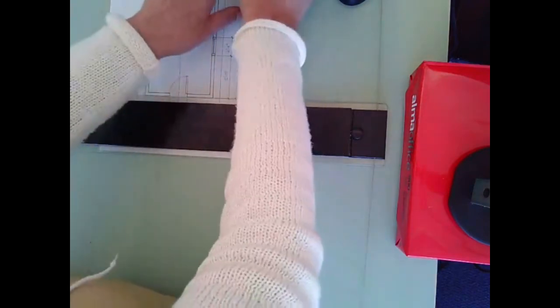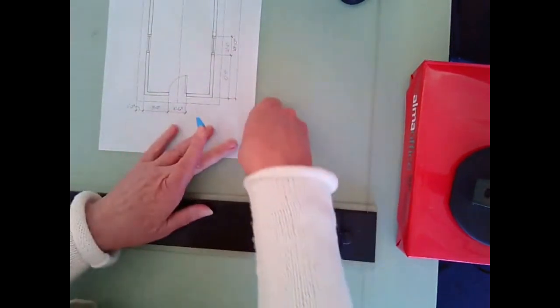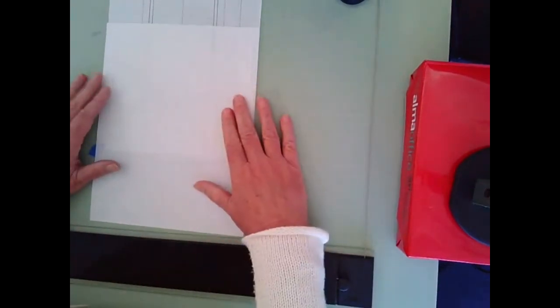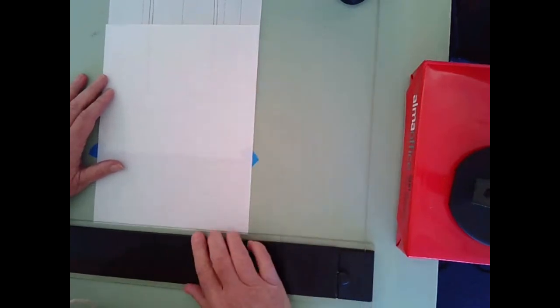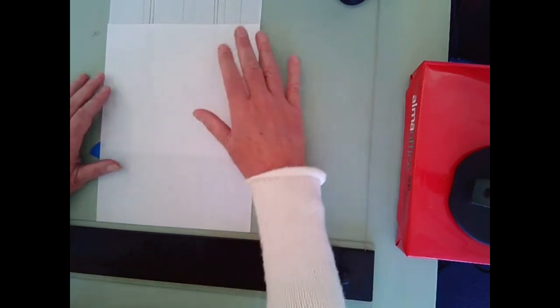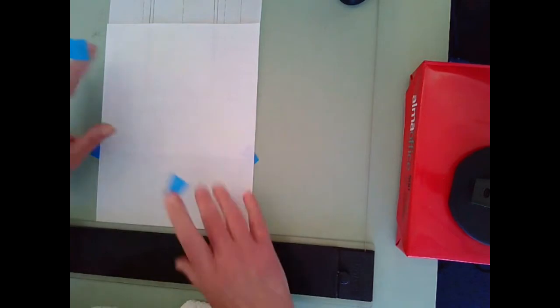So what I need to do is line up the drawing. And when you're doing this, you've got to make sure you line up a line on the drawing, not your title block and not the paper, in case it had shifted at any point in time, so that everything's straight. And I'm taping this if I'm way above the bottom of the board, because I'm going to use this to transfer lines and draw my front elevation. What I'm going to do is put the new sheet of paper on top so it overlaps with the plan. I can see through it. I think you can see the ghost shadow. So I can see through it to get the dimensions I need. And then I'm going to tape that down on top.